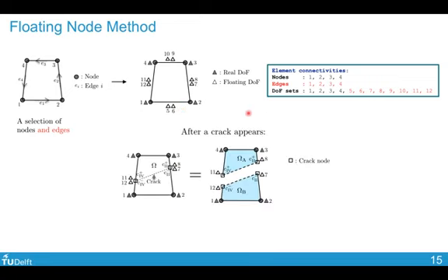When a crack appears, I could activate the degree of freedoms associated with the cracked edges to directly partition this element into 2 sub-elements. And note that these 2 sub-elements, they have everything defined. Once you have your crack appearing in the element based on your failure criteria or propagation criteria, you would then be able to calculate the locations of these crack nodes.